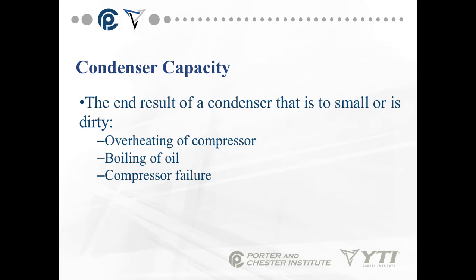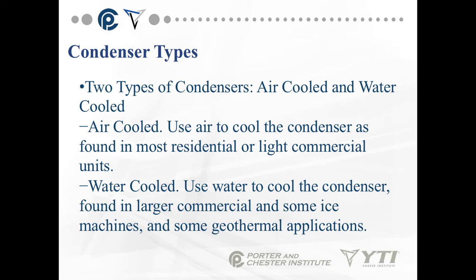Condenser capacity. The end result of a condenser that is small or dirty is overheating of the compressor, boiling of the oil in the compressor, and in turn, compressor failure. Remember I told you in a prior lesson that you have the ability to cause a compressor to fail or to prevent a compressor failure. The biggest issue is dirty condensers. Dirt plays a big issue.